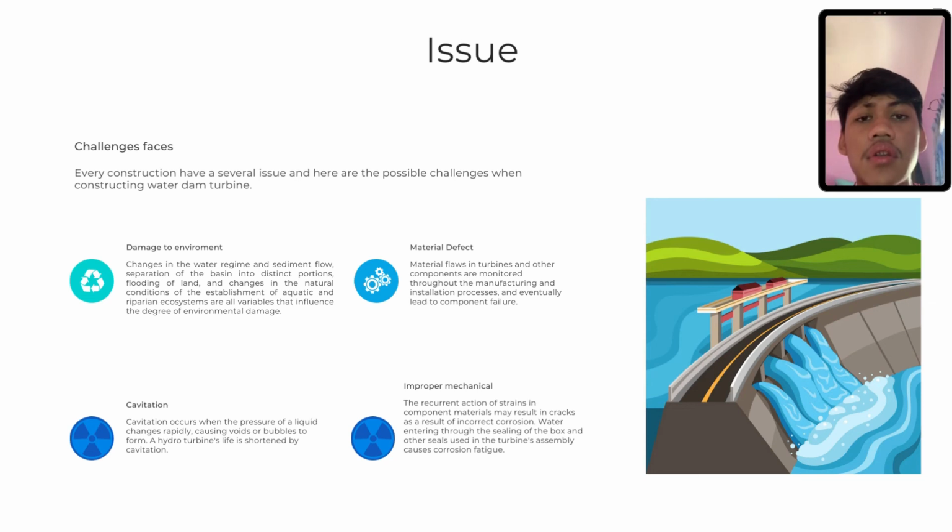Next, there is also cavitation. Cavitation occurs when the water pressure changes rapidly, causing voids or bubbles. This may shorten the life of the hydro turbine. And last but not least is improper mechanical design. The recurrent action of strains in component materials may result in cracks as a result of corrosion. Water entering through the seal of the box and other seals used in the turbine's assembly causes corrosion fatigue. That's all from me, thank you.